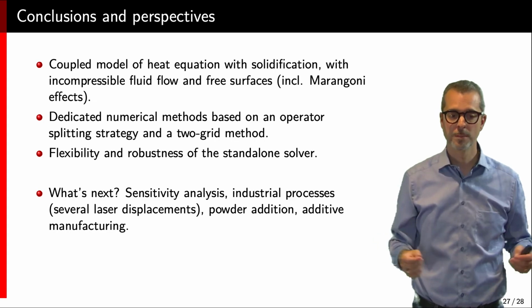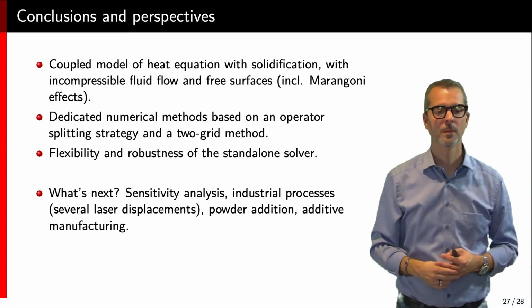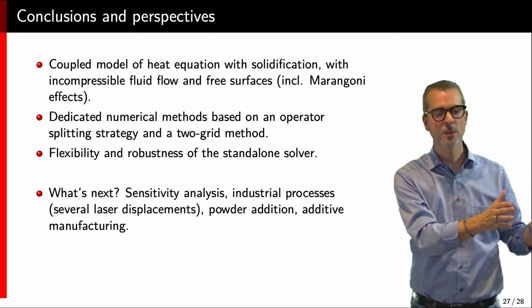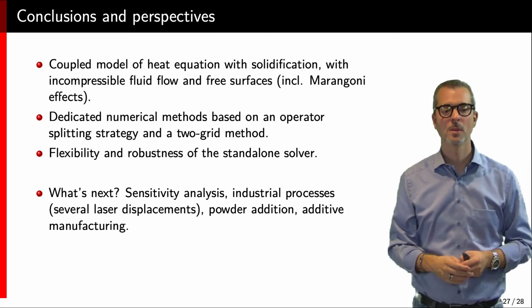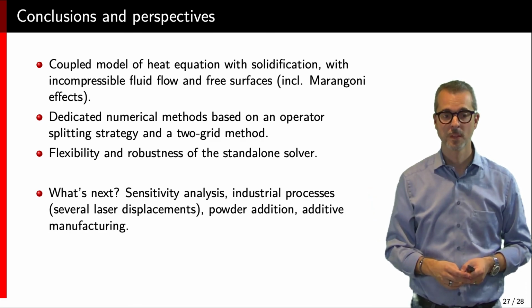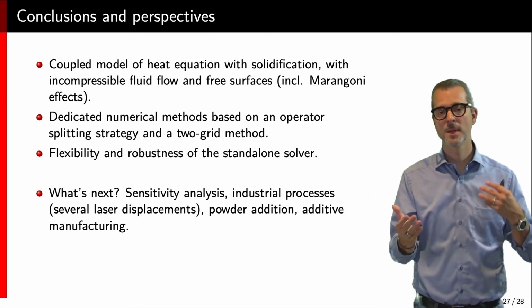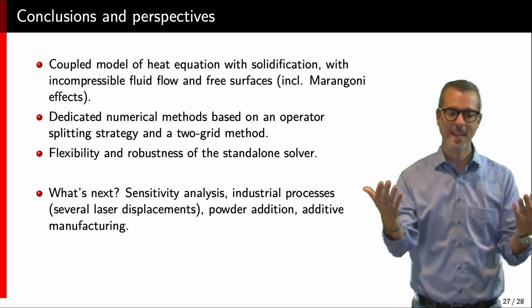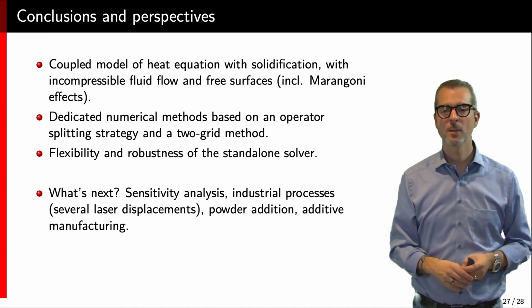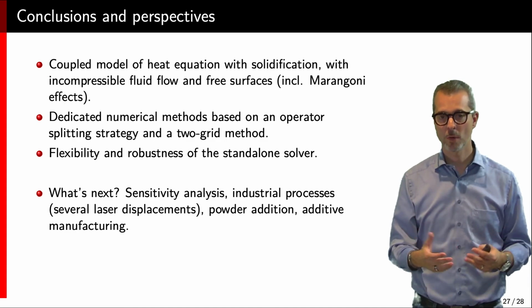Time for conclusion. I showed you a model coupling the heat equation with solidification, free surface flow, and the incompressible Navier-Stokes equation, including the Marangoni effect on the free surface. I showed you a numerical method that is based on operator splitting and a two-grid method. And we now have a standalone solver that is flexible and robust.